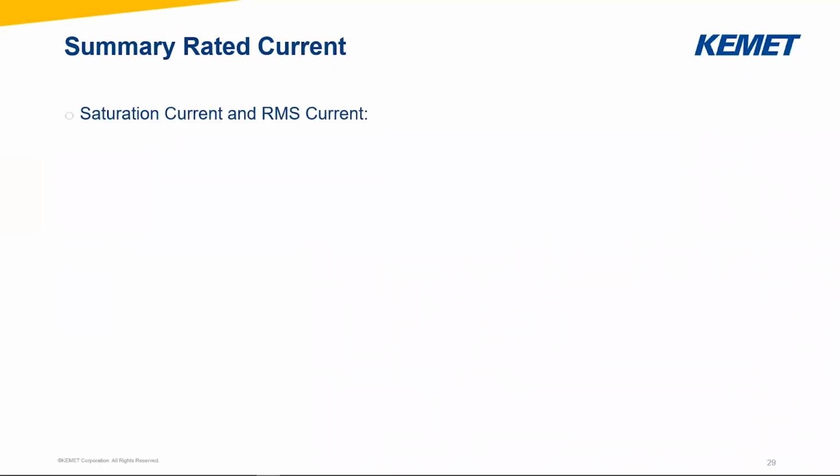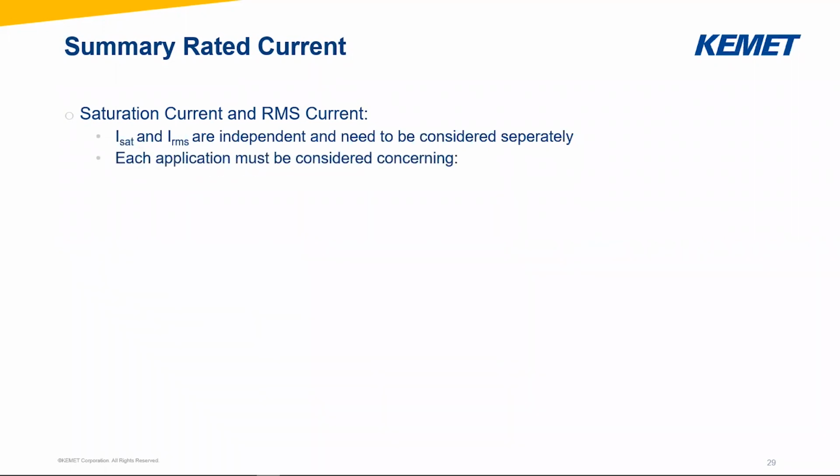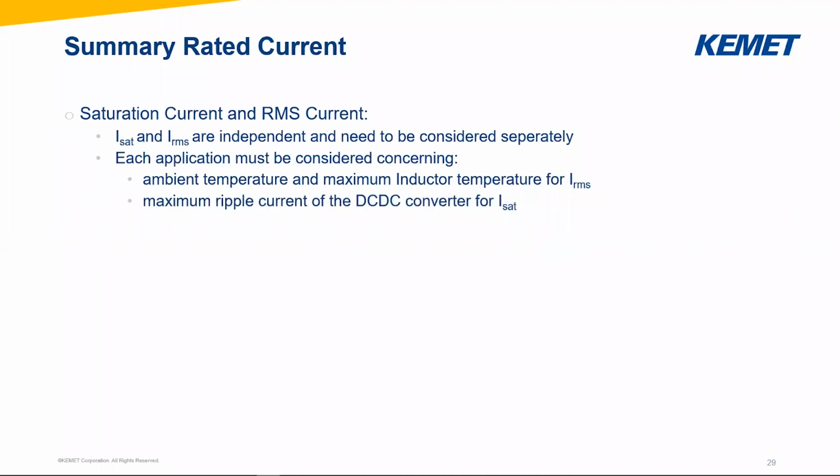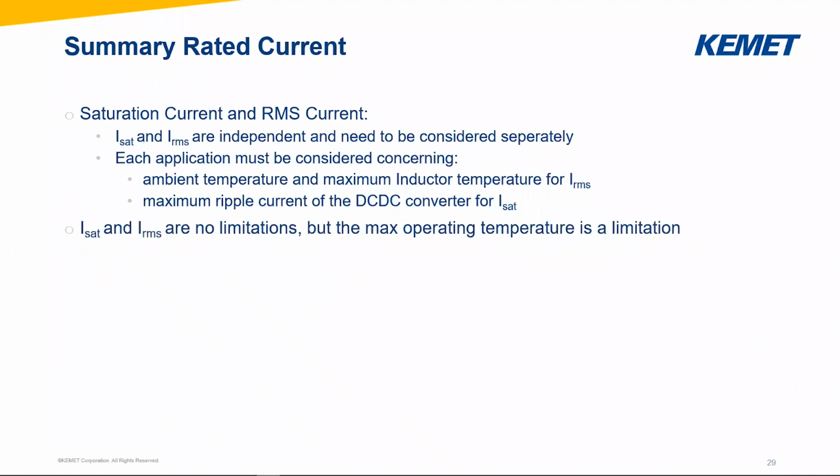So let's make a short summary for saturation and IRMS. Saturation current and IRMS are independent values and need to be considered separately. And each application must be considered concerning the ambient temperature and the maximum inductor temperature for IRMS, and the maximum ripple current of the DC-DC converter for the saturation current.